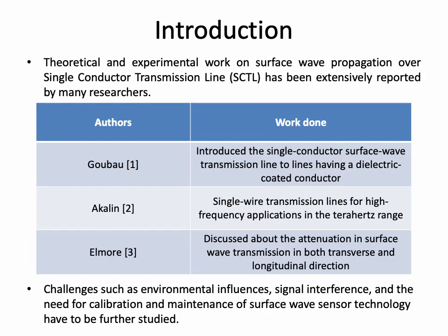So the theoretical and experimental work on surface wave propagation over single conductor transmission line has been extensively reported by many researchers. One such is Goubau, who introduced a single conductor surface wave transmission line having a dielectric coated conductor. In his work, he introduced the conductivity and dielectric losses in the line as a function of thickness of the dielectric layer and dependence of surface wave frequencies on the losses.